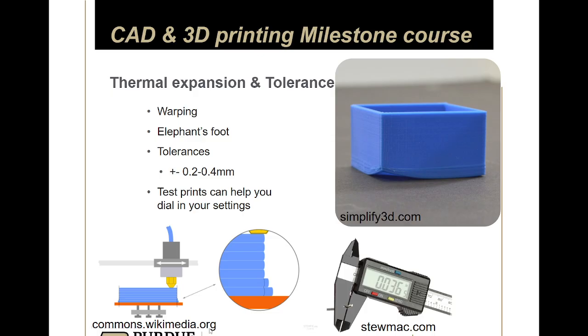But yeah, if you look at some of the things that I design, I just add a buttload of chamfers on the bottom surface, just to prevent that elephant's foot from being a problem if I'm making two parts that interface with each other. Also, it just typically looks a little bit cleaner in general, because it looks nice when you add fillets and chamfers everywhere. So that's what I recommend.